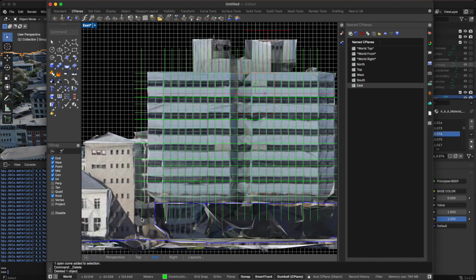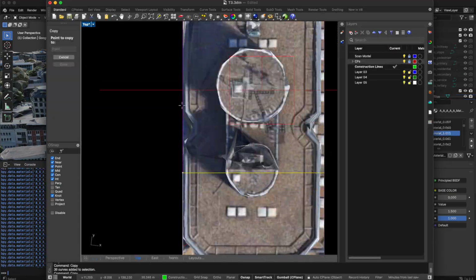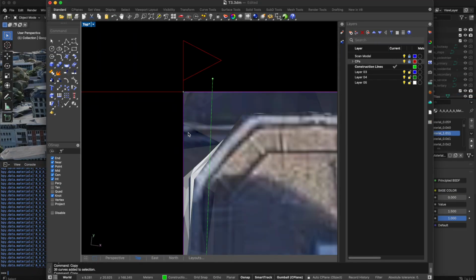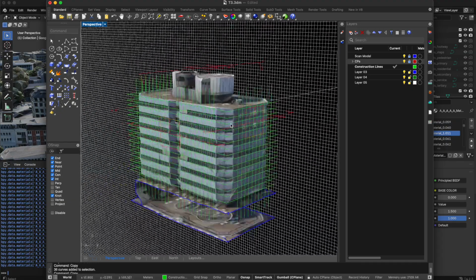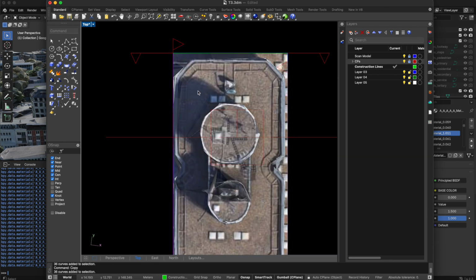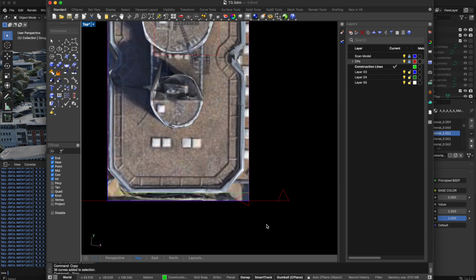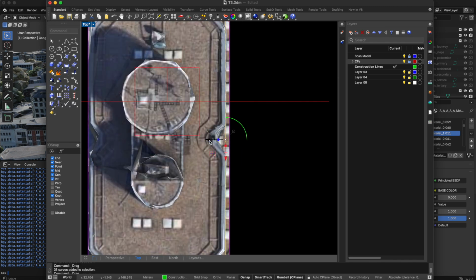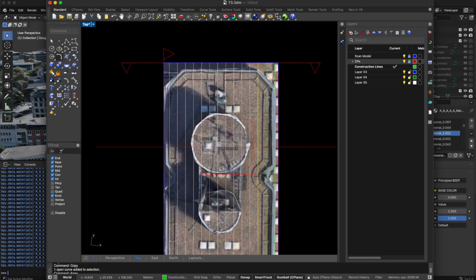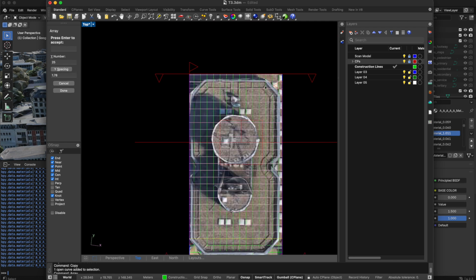I create this grid for the two different sides and copy them to the other ones in the top view. I move the grid to the layer of the facade so that I can combine the two sides to create the horizontal grid for the roof. Using the array command and the distance from the facade elements, we can then easily create it.